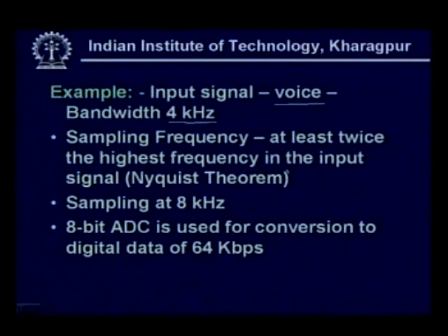You may be asking why the sampling rate has to be more than twice the maximum signal frequency. If it is not done that way, it will lead to a kind of error known as aliasing error. We shall not discuss it further in this lecture. Sometimes the signal is band limited before doing the sampling to avoid aliasing error.